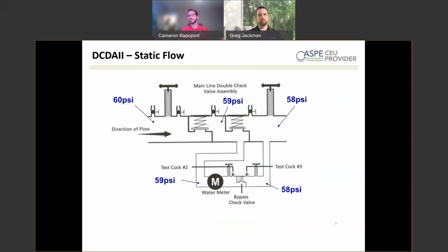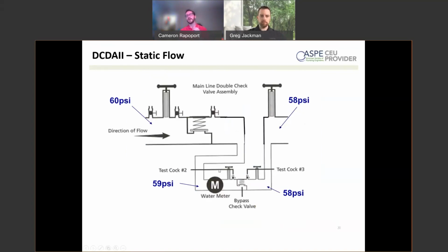So are they safe? Are they protecting against backflow? They are. I like to think of it, with direction of flow left to right, as 2 different backflow preventers. You have your main backflow preventer: 2 checks, 4 test cocks, 2 shutoffs. Then I think of the bypass as part of a backflow preventer that just sizes down to a 3/4 inch after the first check. So you still have 1 check and then a second check protecting the flow through the bypass. You're only bypassing 1 check, so you only need a single check in the bypass.